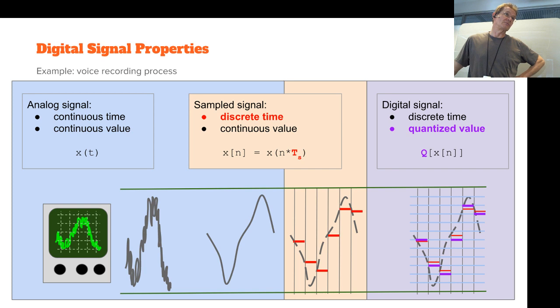And now this is the one we can actually put on the microcontroller, since microcontrollers have very limited amount of memory. So memory-wise, if you have 8-bit A to D conversion, which is not much, then you need that 1 byte there. If it's longer, then you need some 2 bytes, 3 bytes, 4 bytes for each sample. Then you collect the time series of those. You will start actually making tables for those. Okay.